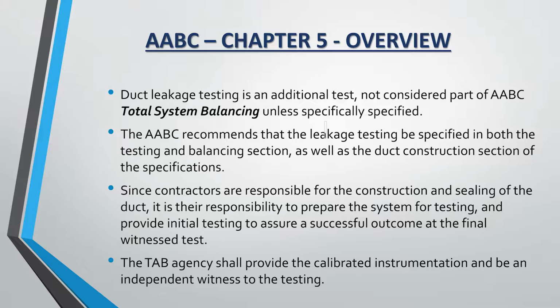AABC recommends that the leakage testing be specified in both the testing and balancing section as well as duct construction. I just talked about that a little bit ago. Everybody understands why that is, so that there's no finger pointing back and forth about who's responsible. Contractors are responsible for construction, the sealing of ducts, their responsibility to prepare the system.